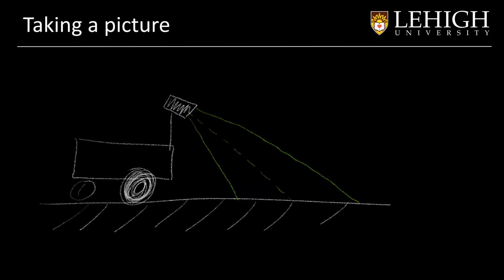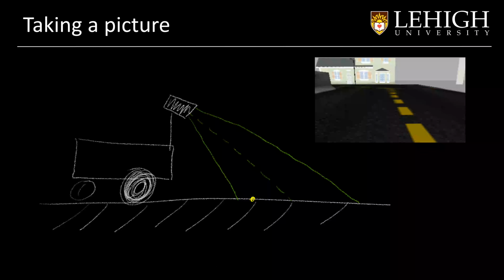Okay, so let's come back to our robot sketch, and our robot detects a point on the ground. When we take the picture, our point is there, right? After applying some image processing, we will see a point that will be in pixels. In the pixels, we can see that we have a coordinate frame in the image that we will denote as u and v. So our point will have coordinates u and v, right? And this is a point in pixels.